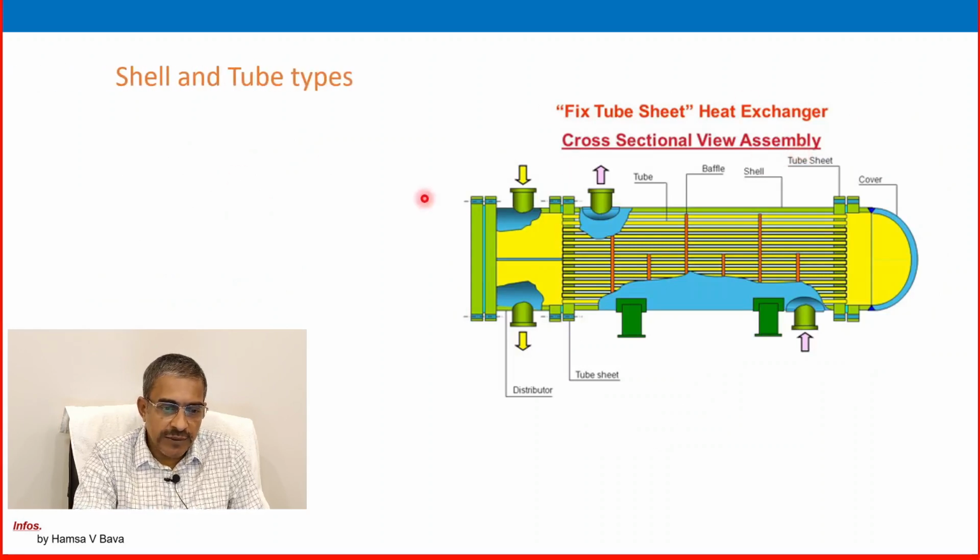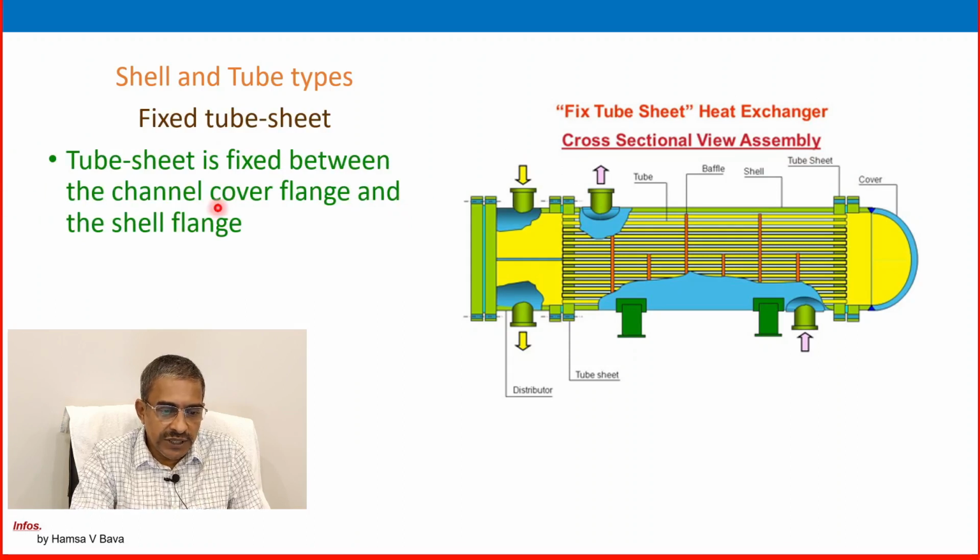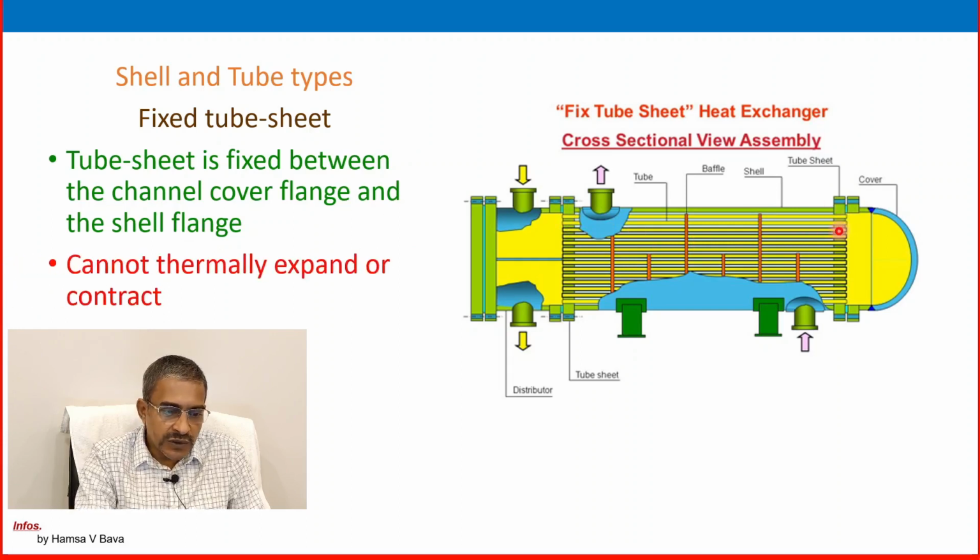So this is also the same, shell and tube fixed tube sheet. The tube sheet is fixed between the channel cover flange and the shell flange here. It is fixed here. See, the channel cover and this one are fixed here. So it cannot thermally expand or contract. This also cannot thermally expand or contract. So in the coming slides, that limitation is overcome.